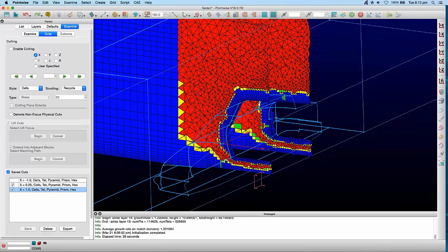Got another question coming through. What do you favour: adherence, negative lift, or drag reduction? It depends on your circuit. Generally, it's difficult to go reducing drag on the car. Whenever you're reducing drag, you want to make sure of the efficiency, so your negative lift to drag ratio, you want it to be better. So if you're taking off drag, don't do it at the expense of downforce on the car.